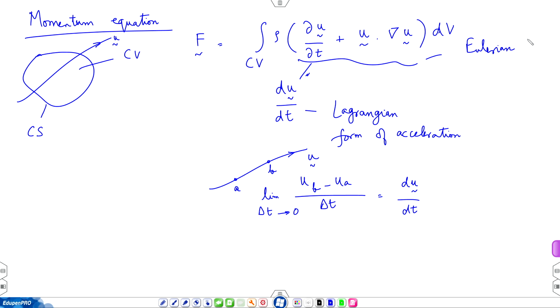Similarly, del u, that will involve the derivative of u with x partial derivative and partial with y. Those are all in x direction for given y given time. So, those derivatives can be evaluated, they do not depend on the prevailing flow field. So, the Eulerian form is what is preferred in calculations.